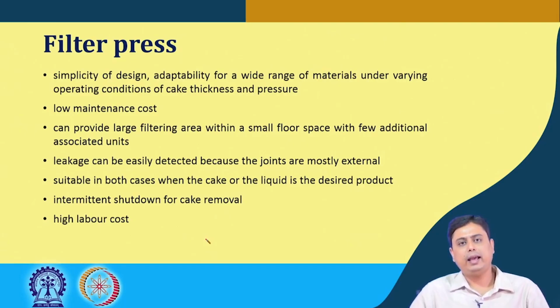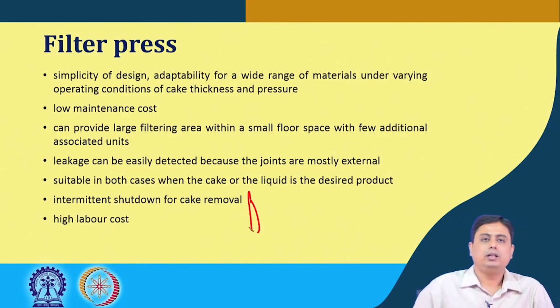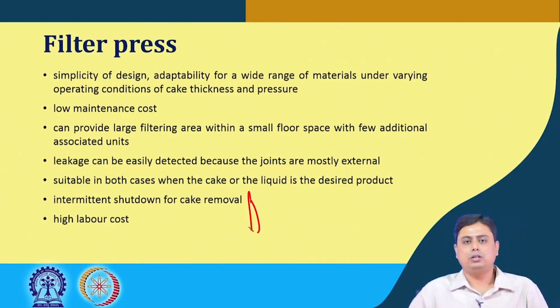cases where cake or the liquid phase, either of these, is the desired or valuable product. In both the cases or both the scenarios, we can use this equipment. But the disadvantages are, as I mentioned, that these are intermittent in operation because the cake has to be removed, and that results in wear of the filter cloth, the damage of the filter cloth after several assembly and disassembly.